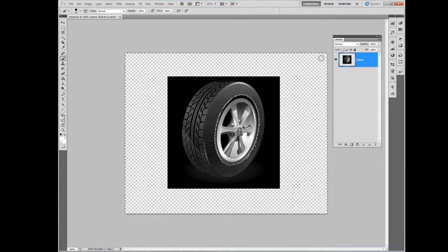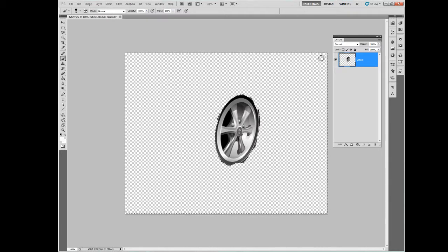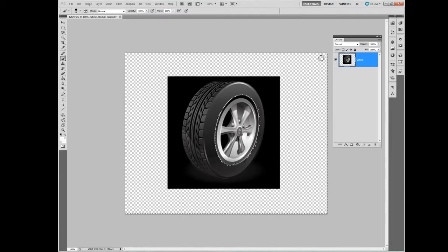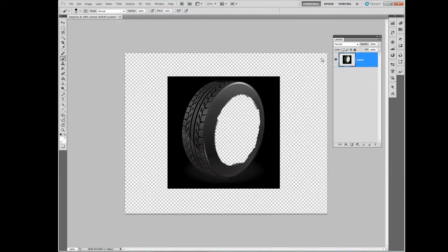And we can actually change this around. This is a good time to go over inverting the selection. Right now, if you notice, I hit delete, and it deletes everything except for the part that had the red in there. I'm going to Control Z that. Now I want to invert that, so it's actually going to just delete the middle. So I'm going to hit Control, Shift, and I. That inverts the selection. So now when I hit delete, it'll only delete what was in the center. I'm going to hit Control Z again to bring that back because that's not really what I want.